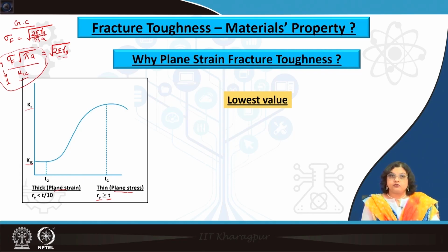When we are talking about failure analysis, however, we are a little bit conservative and we mostly try to figure out what would be the lowest value, so that if we can predict the lowest value, we know that in service, if it is having higher than that least expected value, it will survive for definitely that amount of stress. So, it has a lot of significance in case of failure analysis, that we want to find out the lower limit and not the upper limit in this case.